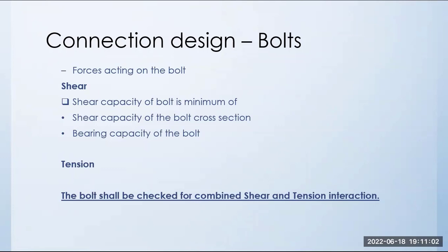And then we take a combined check with tension. Bolts are checked for combined forces as per codal requirement. I think as per the Indian code, it is chapter 10 or something, 9 or 10, or as per AISC, it is chapter H. Combined forces.